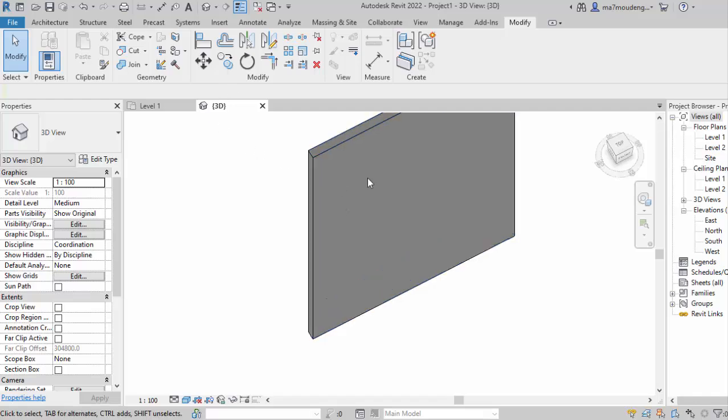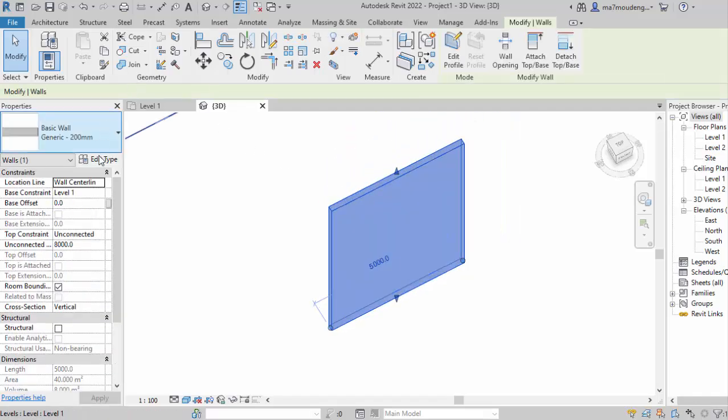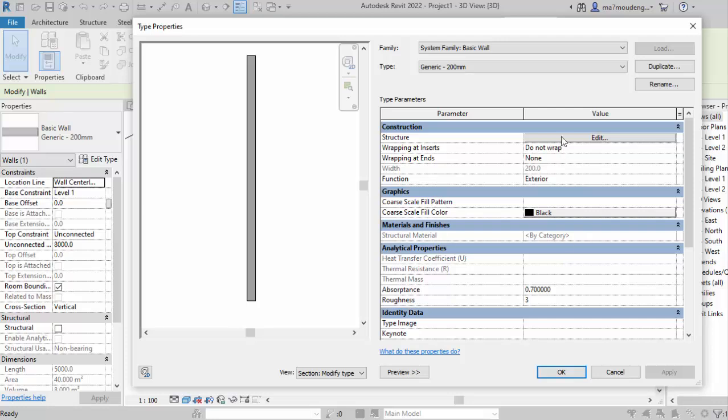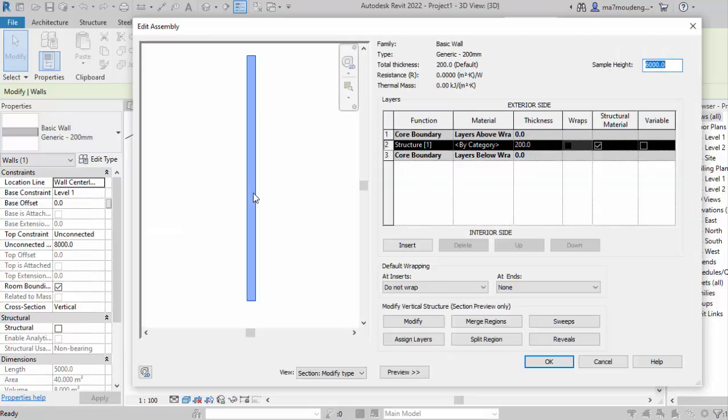So in this case, if I'm creating a reveal or a sweep on the top of a wall, that means I am giving a section of the wall. So let's say that I am making a cut in the wall like this. That means I will give it this profile in 2D, and then the length will be according to the wall. Okay, let's do this practically.